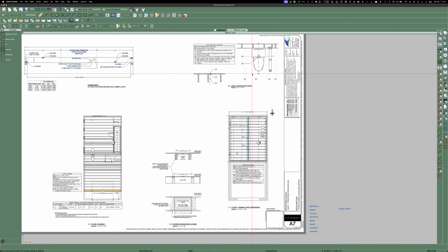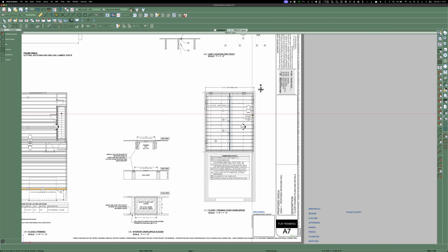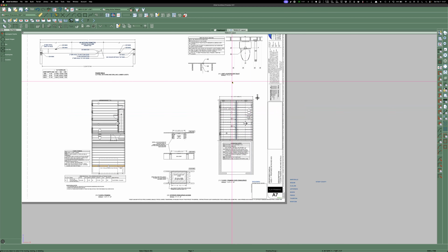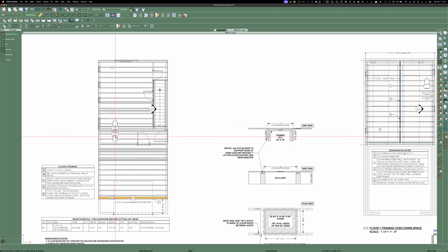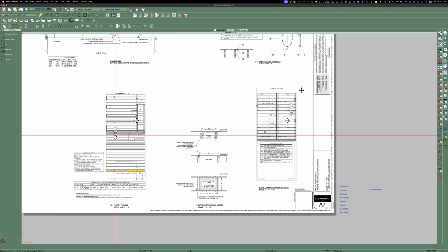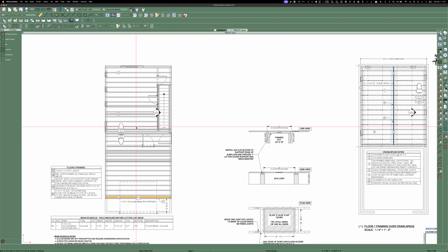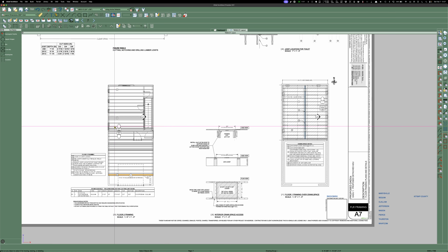When I first started, I was working with some guys, and on one house, we just joisted it, and we're like, whatever. Well, the plumber cut the joist out. We had to come back and double this one, double that one, and box across. So don't do that. Always know where the toilets are. So now that I'm a designer and I do less framing, I'm going to put those toilets exactly where they are on the main floor plan, but I'm going to put it on your joisting plan so that you can be aware. And I might even dimension to them, but that will only become a problem if somehow the foundation's not correct and you're trying to follow the foundation instead of the plans. That's another no-no. Don't do that.